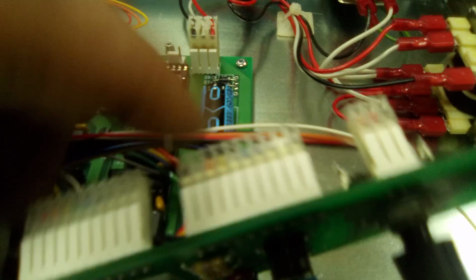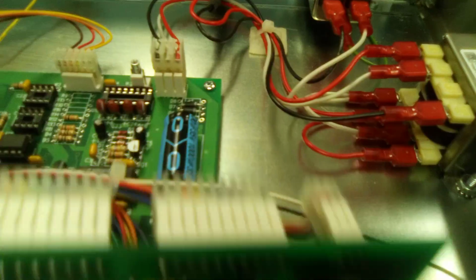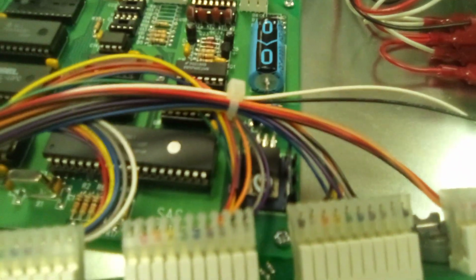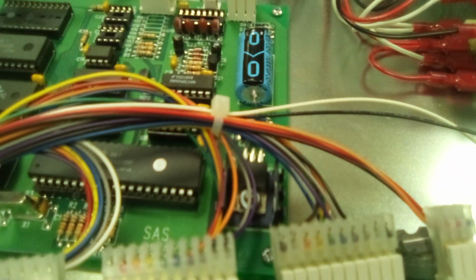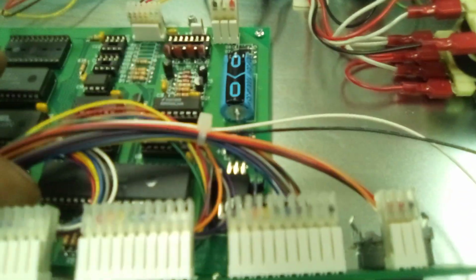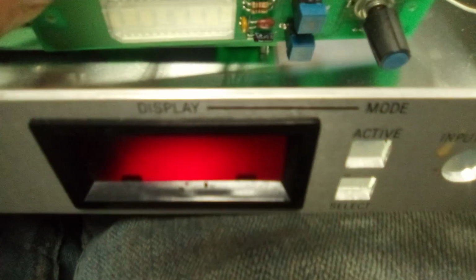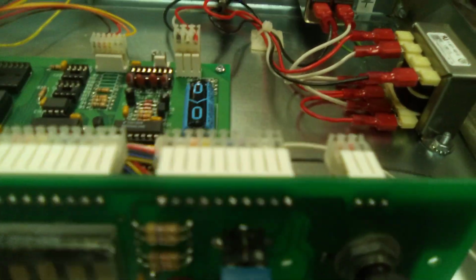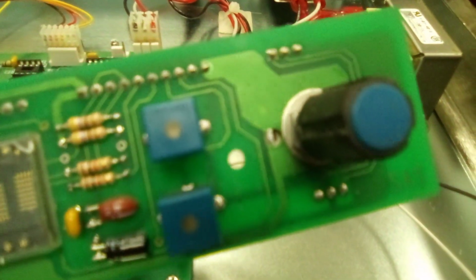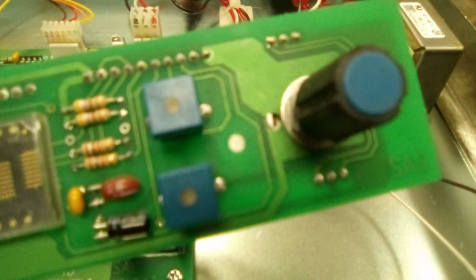And over here, pretty much everything on this is input. So the little knob here, the big old button over here, these two buttons here, there's LEDs in each one of these little buttons too. And I've made those blink before with just a no op. So I'm pretty sure those are just connected to the address bus, such that I don't think you have to write to the data lines to get them to turn on or off. Although I'm pretty sure you do have to scan them.